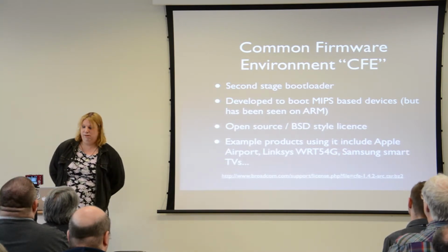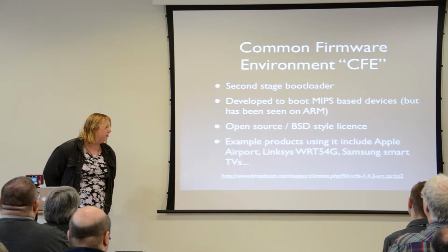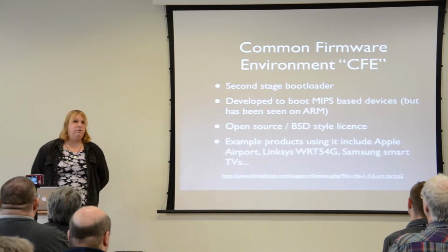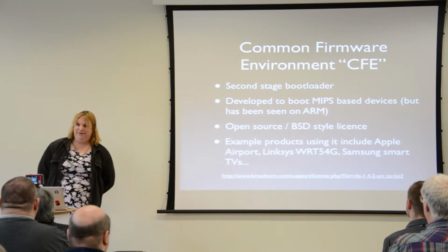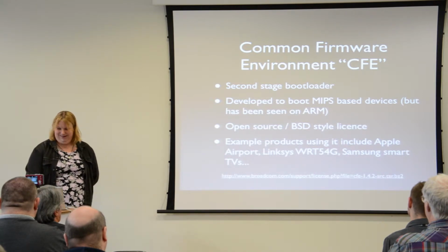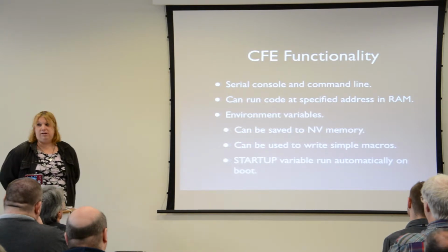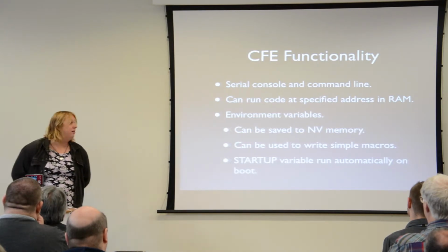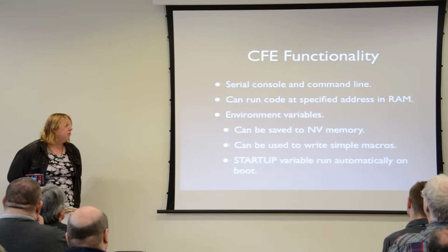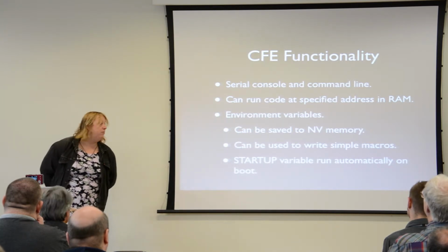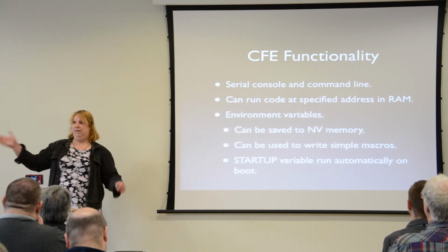And it's in a bunch of things, the Apple Airport, Linksys modems, smart tellies. So if you've got a Samsung Smart TV and you can work out where the serial port is, you might get to a prompt, you might not. It's got a serial console and command line. You can tell it to run any piece of code by just providing the address. You've got environment variables that you can program up so you can make macros. These can be stored so you can reboot. The special one is the start variable, so if you set the value of that, whatever's in it gets executed on boot.